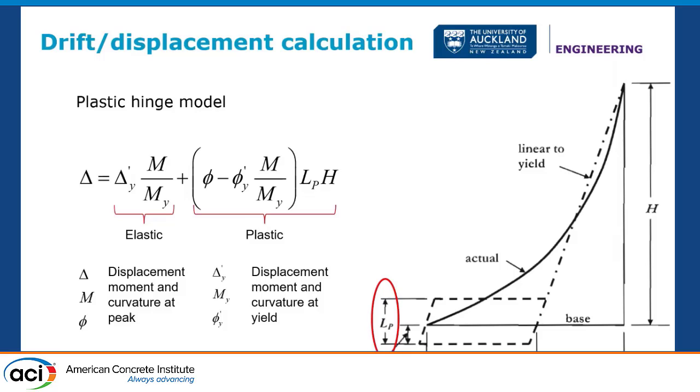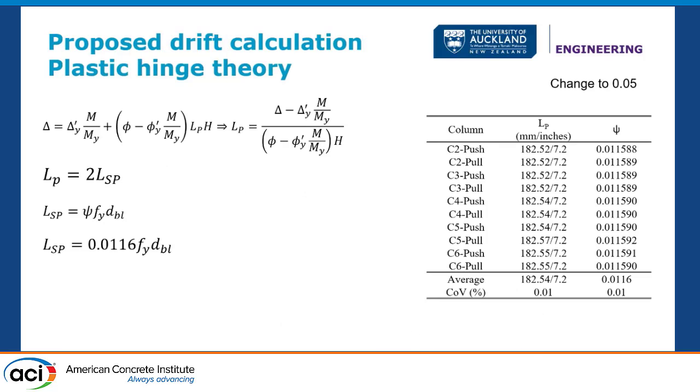And that's the equation where we have an elastic component and a plastic component. Now, what I have done, which is not final, so don't go back to your office and start using this, and then blame me when things happen the way they should, basically, is assume that there is no plasticity at the top, and it's only strain penetration for top and bottom. Probably not correct, but this is what I can do with the test I have.